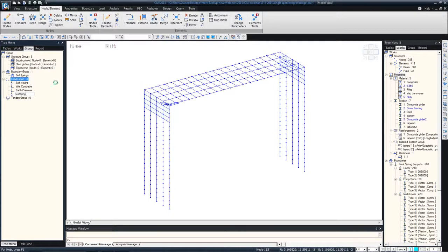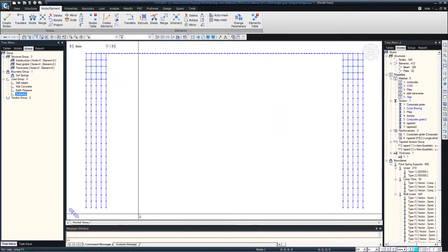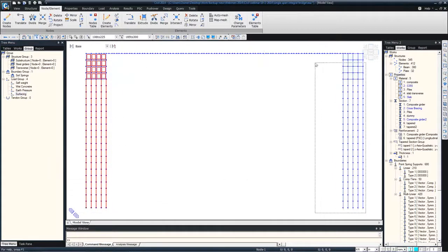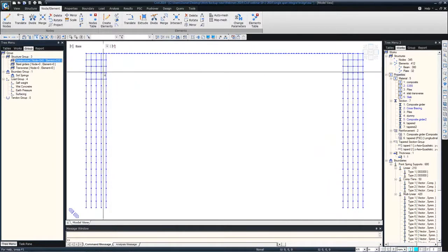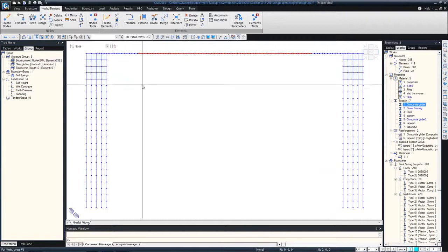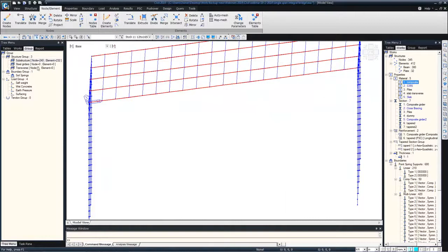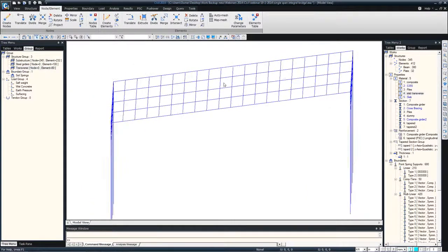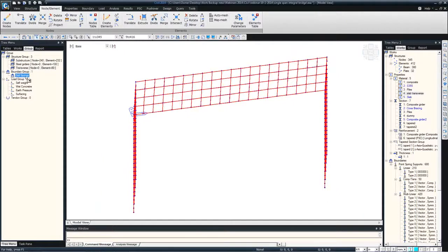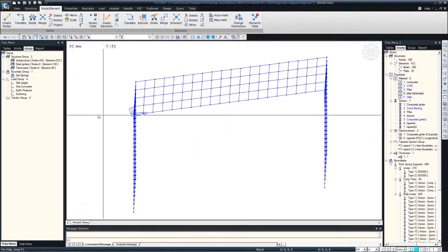Okay. Now quickly I'll assign different types of elements to groups. So I'll start with the piles and abutment first. So just quickly copying all the piles and abutments and drag and drop into substructure. All the steel girders, so double click on the composite material and drag and drop into steel girders, and double click on slab transverse, drag and drop the transverse members. Then select everything, drag and drop into soil springs to include all the boundaries in the structure into the soil springs group. And for self weight and wet concrete, we'll see when we apply the loads.